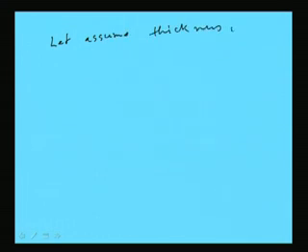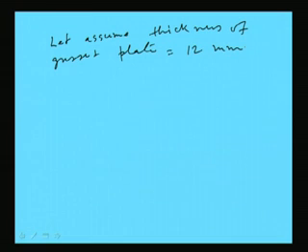First, we will assume some thickness of gusset plate. So, to start with, we have to assume some thickness. So, we have assumed say 12 mm, because 10 mm thickness was for all the plate members. So, we are considering say 12 mm.